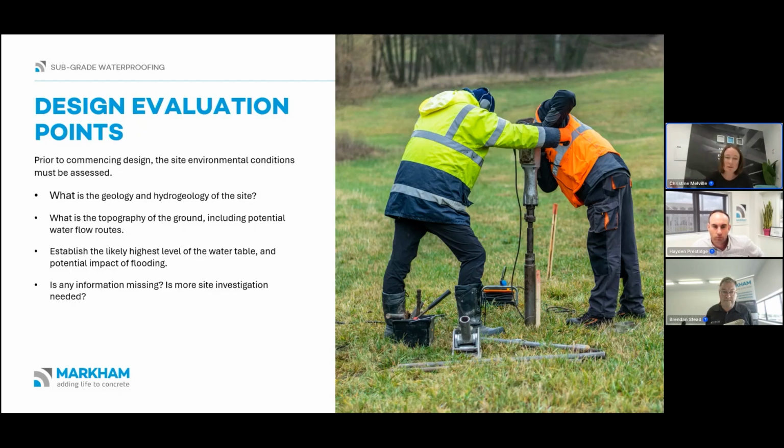I'm sure a lot of our NZ people are familiar with the 1 in 100, 1 in 500 year rain events that we've had around the country, and we've got to be thinking about those in a design sense from the get-go, and be really thorough and extremely risk averse when designing these things, because that is part of what needs to be proven for the BS 8102 standard system, and being guided by that means that we're starting to adopt those strategies.